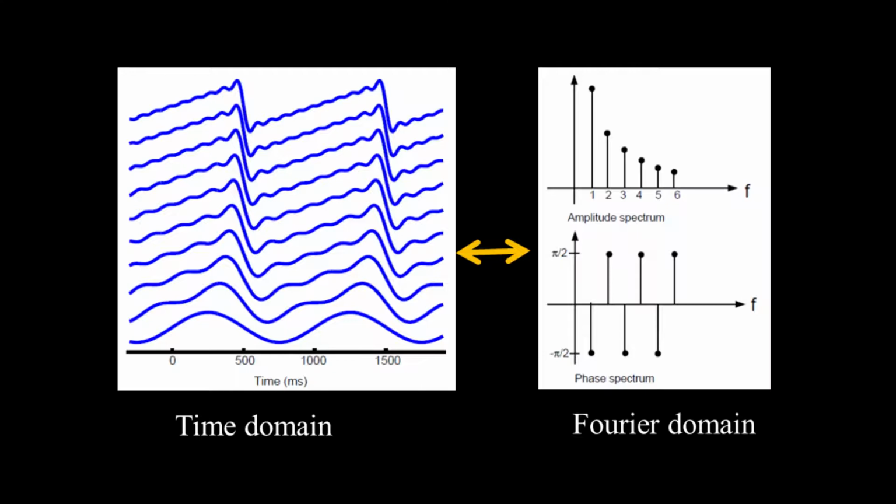The sum of the cosine waves of the sawtooth wave is shown on the left. Each successive trace contains one more term than the trace below. As the number of terms increases, the resultant signal approaches the sawtooth waveform more closely. It is interesting to see the effect that changes in the phase spectrum have on the resultant waveform.